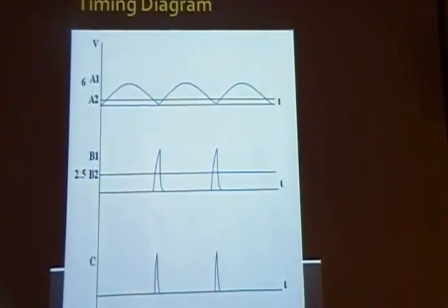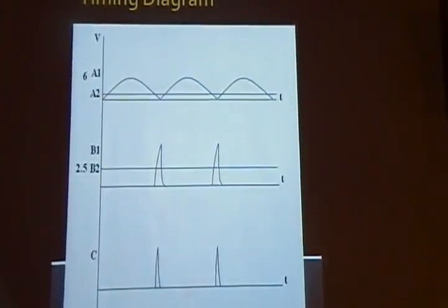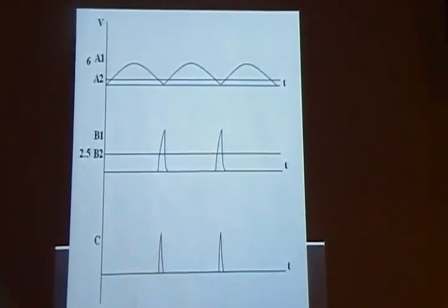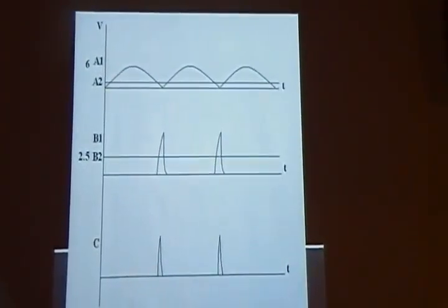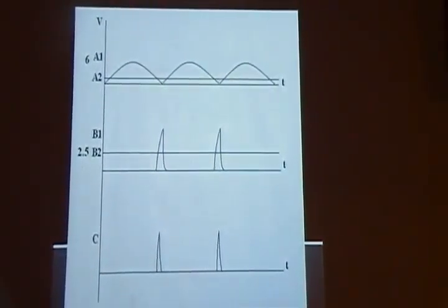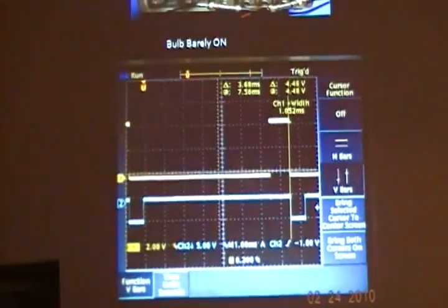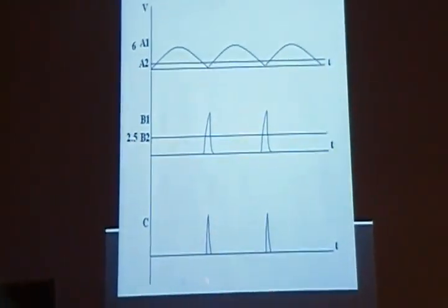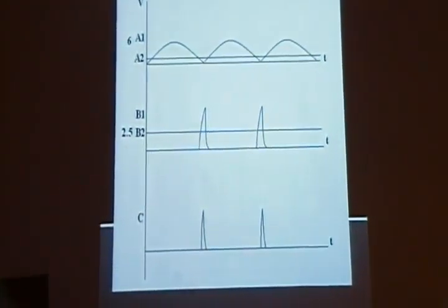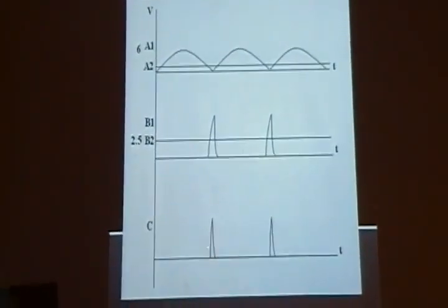So at this point of time, when we had the circuits, we tried to test it with a pulse generator, and we found out at the first test, the lights were still flickering. When we went further, we found out that the real thing to control the intensity of the lights depends upon the timing. What I mean by that is, when you have the first trigger here and a pulse is generated, the pulse needs to be stopped right before the next zero crossing.